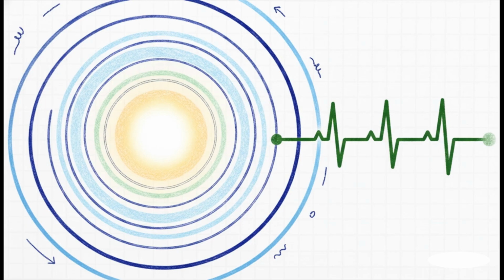Let's deconstruct that formula a bit so you can truly see the physics hiding within the math. The mu naught part: that's just the source strength. But look at the 1 over r in the denominator. That reveals that the wave's amplitude inevitably dilutes as it spreads outwards. It's inversely proportional to distance. And that complex exponential term, e to the negative j k naught r, beautifully captures the phase delay. It is literally the mathematical heartbeat of a wave propagating outward through space and time at the speed of light.